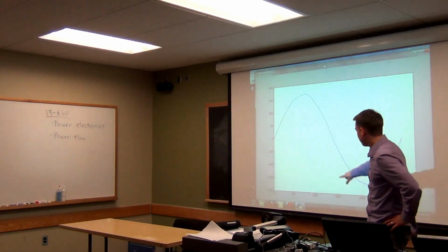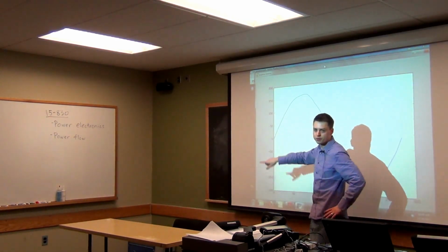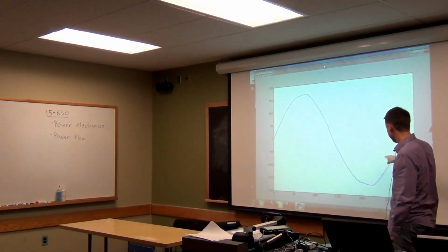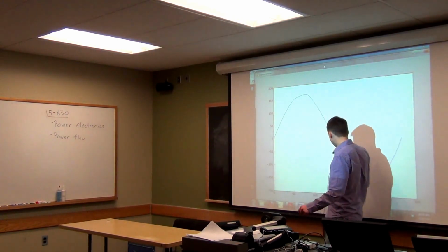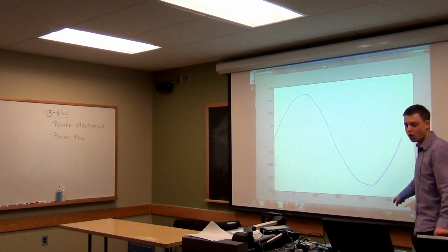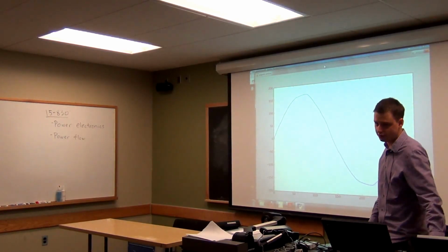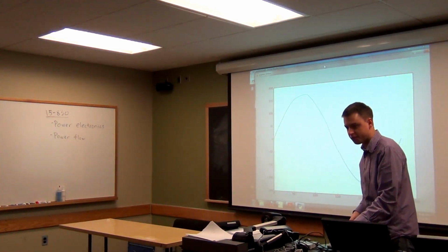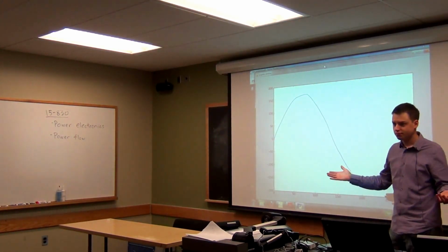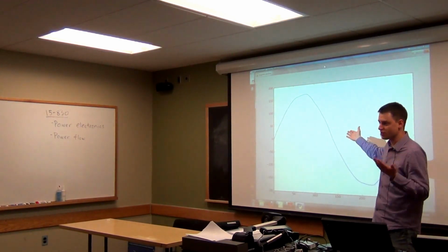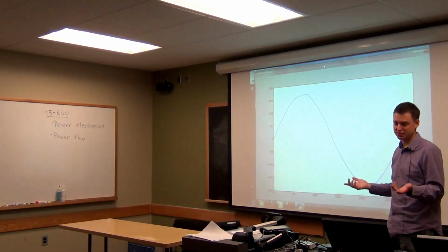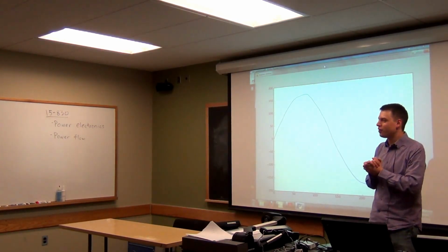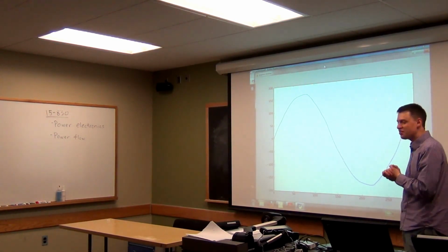And this axis here is voltage in volts, and this axis is actually its number of samples. So this goes under 160 hertz. So 160 hertz, we're getting about 200 samples or 250 samples or so. What's really happening is we're sampling this at 16 kilohertz. So we're sampling this voltage pattern at 16 kilohertz out of this guy here, and then we're plotting what it looks like. So if you only sampled it once or twice a second, you wouldn't be able to see this at all because, of course, it goes up and down 60 times a second. But we're looking at it in very, very high resolution here. Actually, you can go higher if you want to and do some really crazy stuff. But we're at a reasonable resolution here.